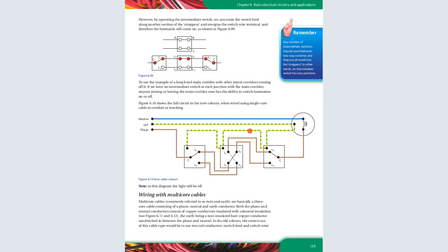So you can see how the wiring is done. This is the neutral, this is the earthing wire. They go straight to the bulb. This is the phase, connects to line 1, and then it's joined to line 1 again, and then it supplies power here. So when this is linked, this gives line 2. Line 2 is again connected to line 2.